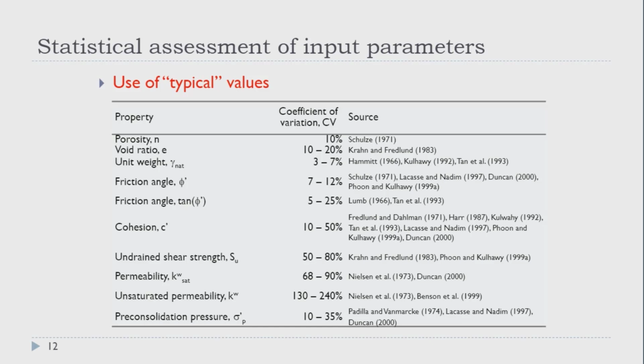So that means that in a slope stability problem, we want to take into consideration the impact of friction and cohesion or undrained shear strength, because that will allow us to know the level of uncertainty of our factor of safety, and it will depend largely on whether the material is dominated by friction or cohesion, or if it's a situation where we have undrained shear strength. So, yeah, we have several options.